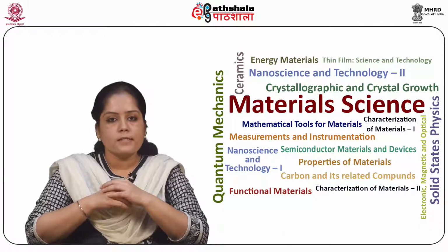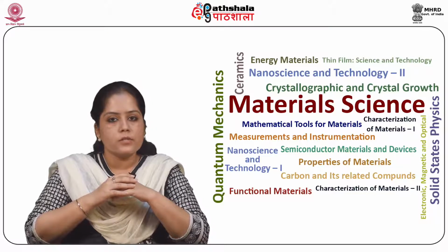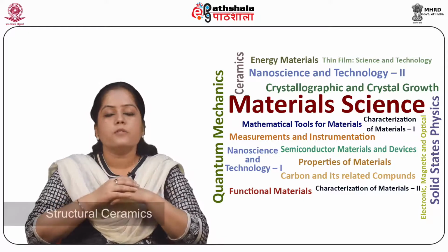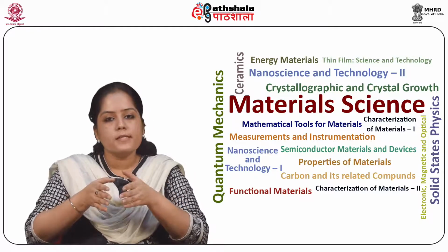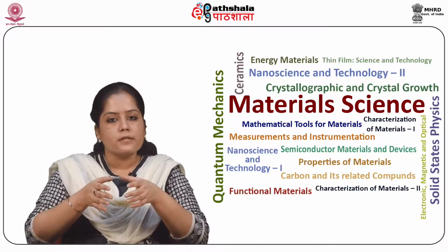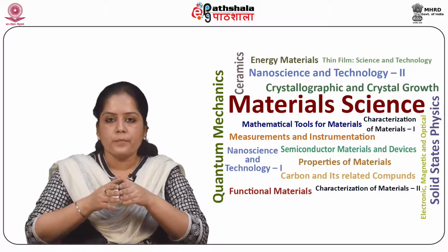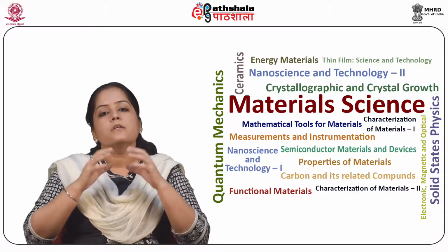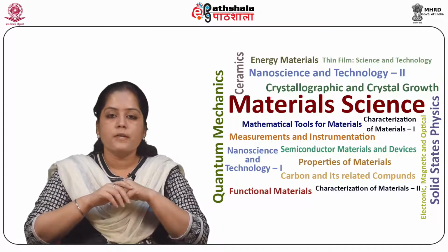So students, let us start with a brief introduction about the module. The ceramics which are used in applications where their mechanical properties are important are called structural ceramics. Mechanical properties include strength, modulus, resistance to fracture, creep, wear resistance, etc. Ceramics tend to fail by brittle fracture. This is the most important factor limiting the use of ceramics in structural applications. So resistance to brittle fracture is therefore the most important property of ceramics.